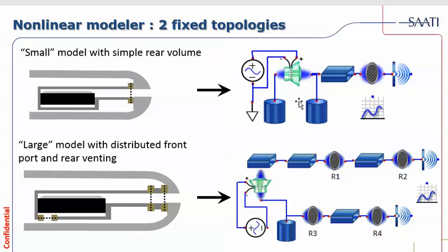This topology here is meant to mirror that. Here the speaker is meant to represent this speaker. This rear volume is the small rear volume in back. The port leads out here to the material. Then here's the material. And the radiating port actually does allow you to enter a port length inside. So this little port extension here is specified in the radiation element.